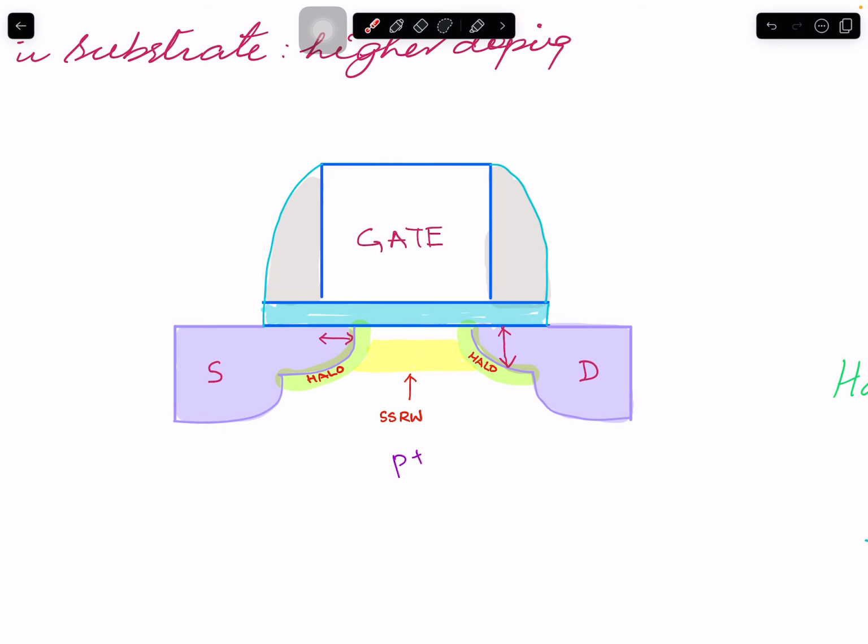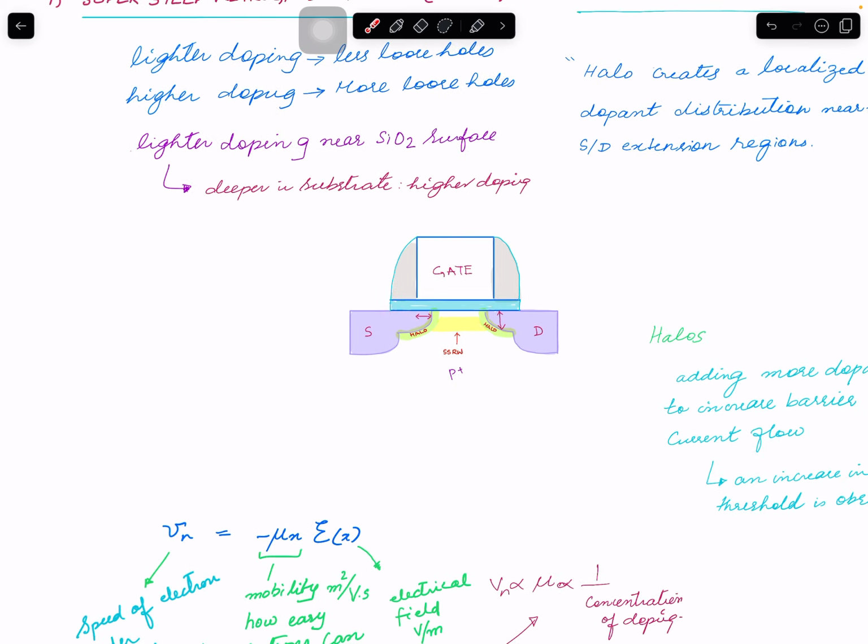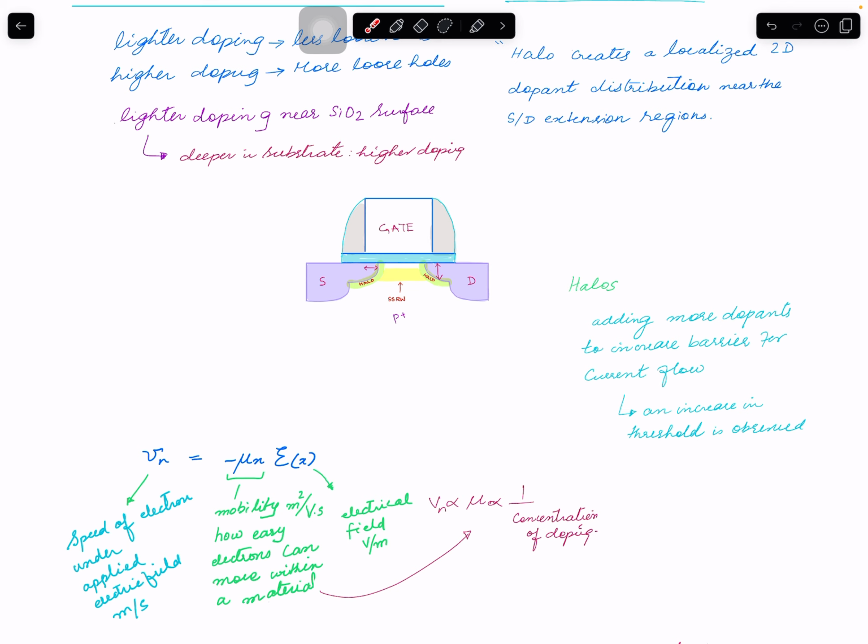So as I said, it's not super complicated, just try to understand the basic intuition. Sorry, I keep going back and forth. Researchers found out, as they were shrinking the transistor, that the problem is in this region. Before, we had a uniform concentration of doping, right? This is a P plus area. It means impurities were added to silicon in order to make more hole carriers and fewer electron carriers. Because we don't want current flow here, and we make this P plus because it's P, this is N, this is a reverse bias, so it's a blocking thing here.